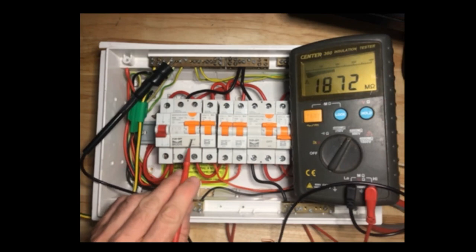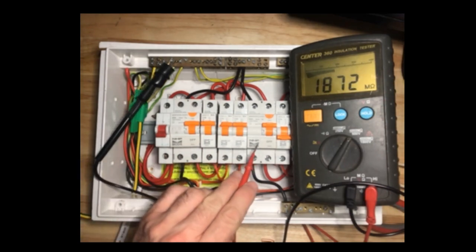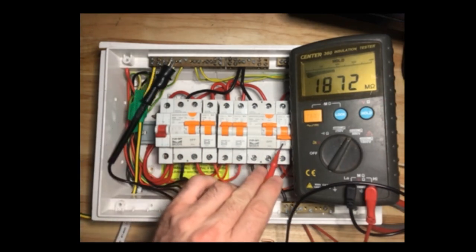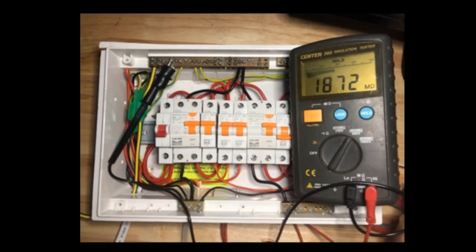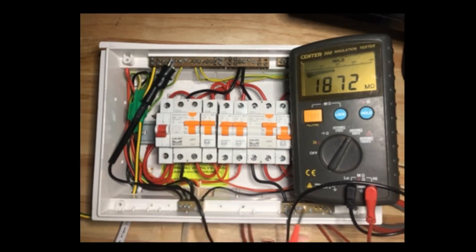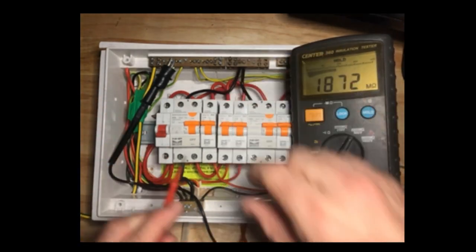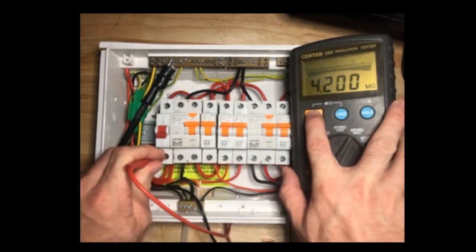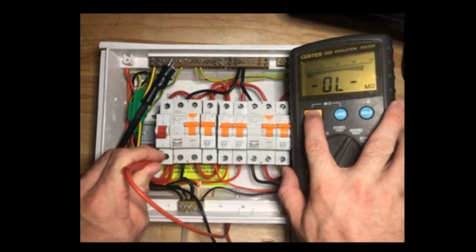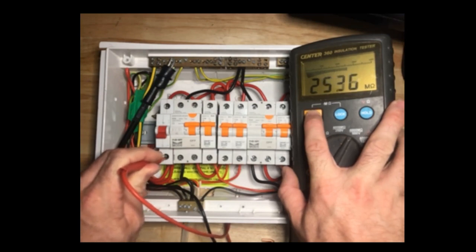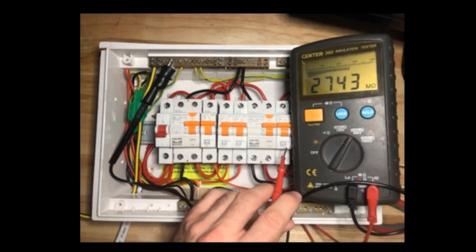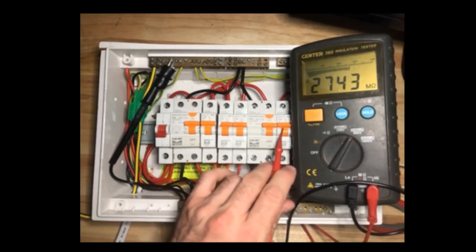So that just confirms everything connected on these devices here is fine. This one is the faulty one. And I'll just, off camera here, remove the fault that I've put onto the installation. So I've gone out, figured out where my fault is, and I can repeat my test here. And we should see that the test is now passing. See 2,500, plenty high enough with this breaker turned back on where we had our fault.